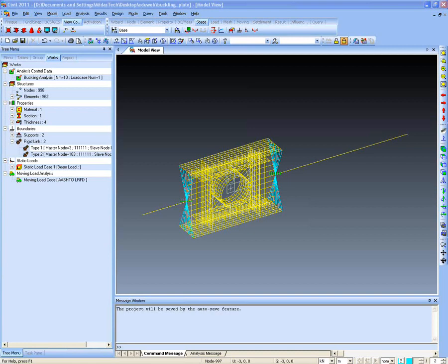Mr. Antino asked, can a frame element be switched to a plate element with any special function starting from the frame section definition? Sir, we can, as I showed in my presentation when I was modeling, that you can extrude the node into a line element, and the line element can be extruded to generate the plate elements. So this is how you can do it.